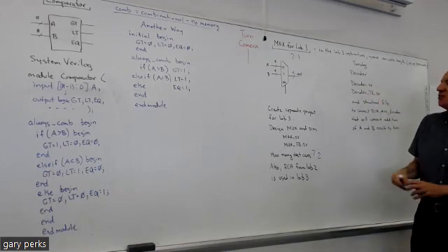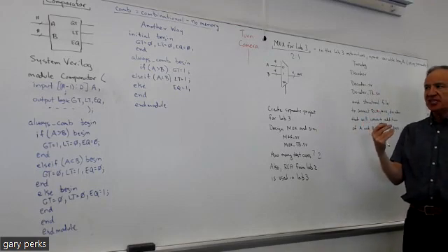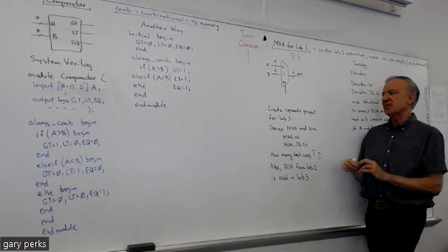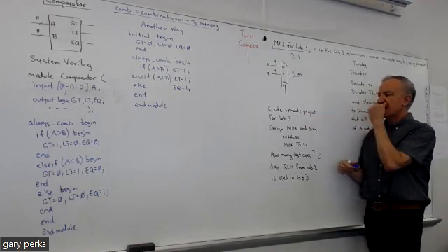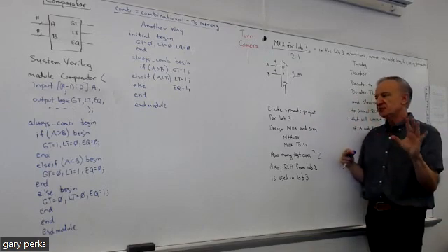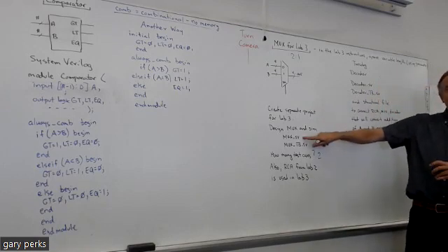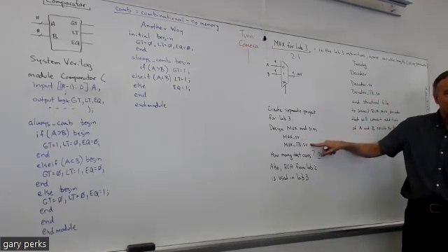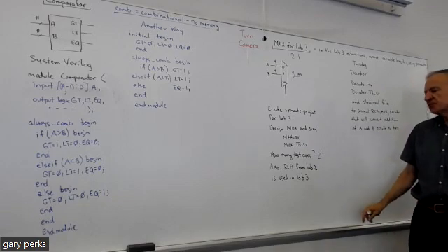So what you can do, after you do the activity day today, you can get started on lab 3, but like I said, you can't finish it until we talk about decoders on Tuesday. But what you can do today after the activity is create a separate project for lab 3. Again, I hope you're doing that for all the labs. And then go ahead, design your mux with an if statement. That's gonna be your design source. Go ahead, do the sim file. It's only gonna have 2 test cases. Simulate your mux. If it works, great.